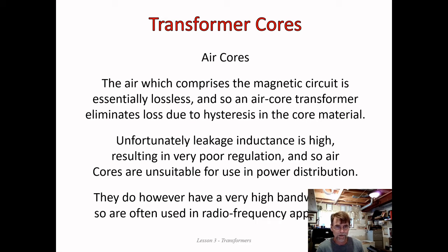The final statement there says very high bandwidth, so it's good for radio frequency applications. As you increase the frequency, you get more changing of direction, the flip-flopping of the magnetic field and the changing of the direction of the current. So back to that word hysteresis, it's not a problem in an air core. An air core is probably the way we want to go in extremely high frequency applications. For our typical power distribution at 60 hertz, air core is probably not the right choice, and it really never is.